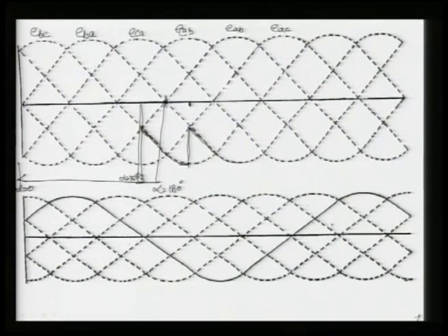again 60 degree here, where your valve 5 is fired, here valve 4 is fired. We are writing the valves where it is giving the gate pulses, because you can see the difference between here and here, it is 60 degree. So, next 60 degree here, and it is a sequential firing, means 3, 4, 5, 6, 1, again it is a cyclic one. So, it was here, then it was coming here, and now we have reached here. Now, your valve 5 is getting the pulse.